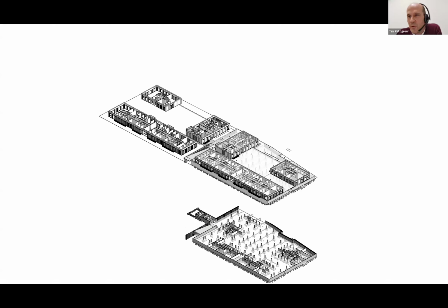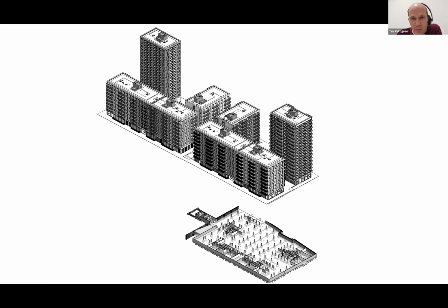So all we had was cores and facades, and everything else was picked up by transfer slabs that were picked up on the prefabricated panelized system. That made it a very different structure. So as you can see, the top levels all repeat, all stack on top of each other, very simple.